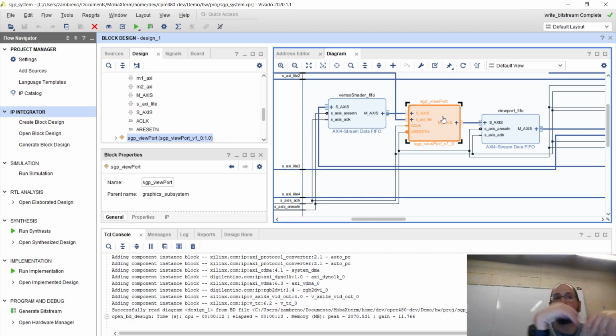But you then have the ability to add as many status and configuration registers as you want. They just have to hook up to the AXI-Lite interface. So AXI-Lite checks a certain address range, reads or writes to a particular register in that address range, and you will wind up saving time by adding lots of status registers in your design. The one that I personally think is the most valuable is a status register that just encodes a value for, this is core version number 22. Because I've just made a change to the core and now it's version 22. And I'm going to make another change to the core. You're making a very small tweak. I need to update that register to 23.